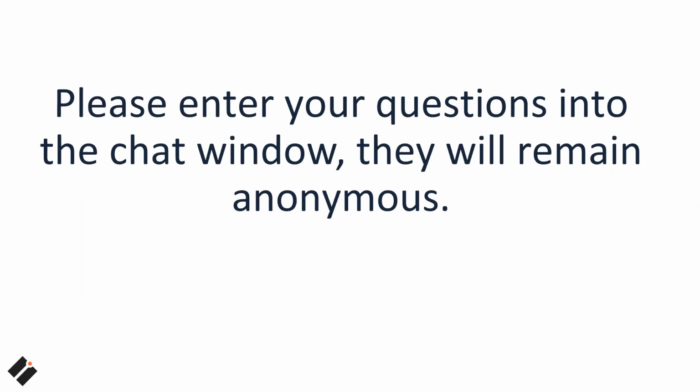Right. So what we've essentially done is we've pre-built a lot of manufacturing connectors and manufacturing protocols within the Cortex environment. So there's no customization required for these connections to data systems. What essentially has to happen is a configuration. The connector is ready to go. You configure it with the connection settings, so the server settings, the tag, and the information that you're pulling, whether it's a historian, a control system, or even a data lake. There are different types of protocols. So OPC, MQTT, even Modbus to directly speak to a PLC. This information is all pipelined and pulled into a central store, and the context is then developed and built on top of that central store.